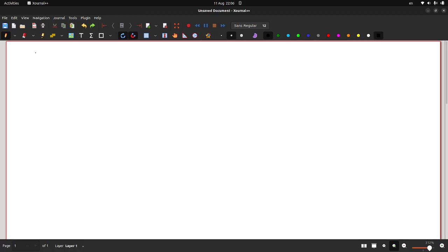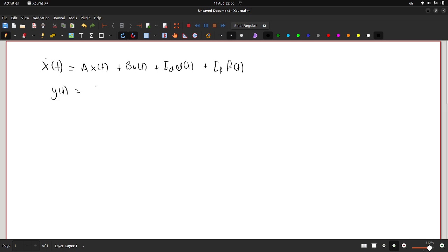Let's do a quick recap. So, as we said in the last session videos, x dot is equal to Ax plus Bu plus E_d times the disturbance signal plus E_f times the fault signal, and y of t is equal to Cx of t plus Du of t plus F_d d of t plus F_f f of t. Let's denote this as the first equation and this as the second equation.